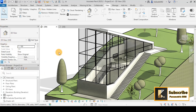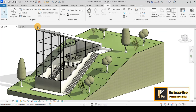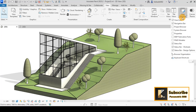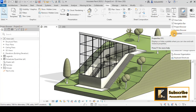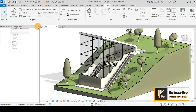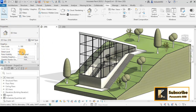Something else we can talk about is, if by accident the properties has gone and the project browser has gone, how can we return it back? We can go to view, user interface, and then click on project browser. As you can see, it will return back, and also the properties. If it is gone accidentally, by clicking on the properties, you can see that it will be back here.